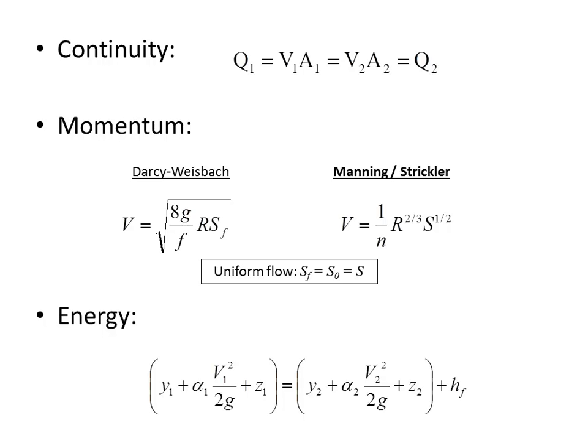These are really the main equations that we're going to use for the rest of the semester. In a sense, you don't even need an equation packet because you could memorize these equations pretty easily, particularly because we're not going to use Darcy-Weisbach hardly at all. It'll just be continuity, the Manning equation, and the energy equation. And with those three, we're going to be able to understand phenomena like the changing channel width, the hydraulic jump, and a lot of things in between.